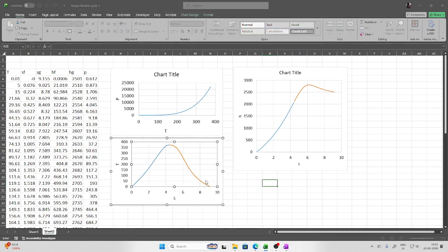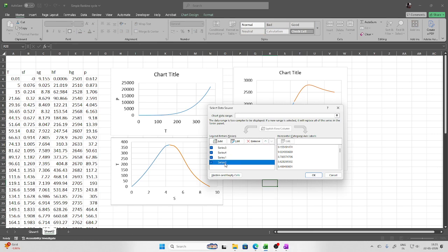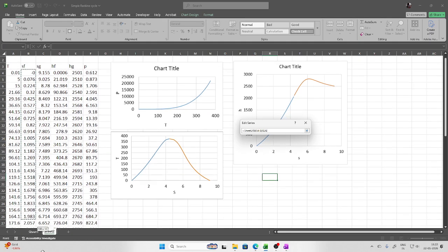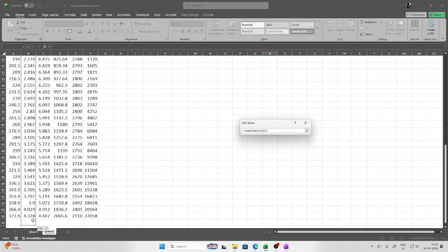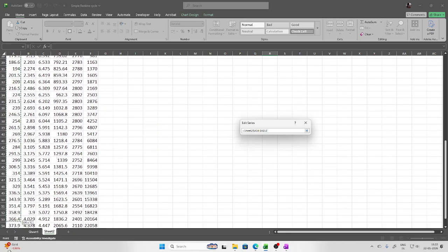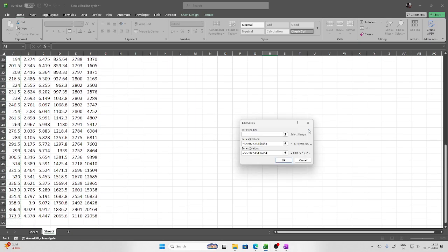let me do it once more for you. So I'll delete every series right now. Remove, then this also remove. Okay, I'll add new. So now the x-axis is entropy, for temperature entropy. For entropy, first I'll select SF as the first curve. Then the y-axis will always be temperature. So this is the one.